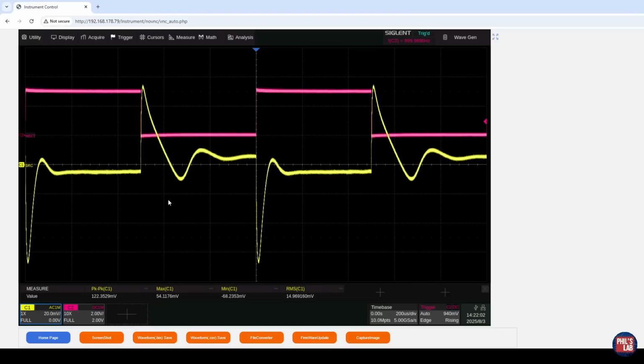So what you could do is you could sweep through all these different frequencies, 1 kilohertz, 10 kilohertz, and so on, calculate the RMS voltage noise, and divide that by your load current and get an approximation for your power distribution impedance. But of course, we can automate that, and I'd like to show you how to do that other than using a Bode 100.